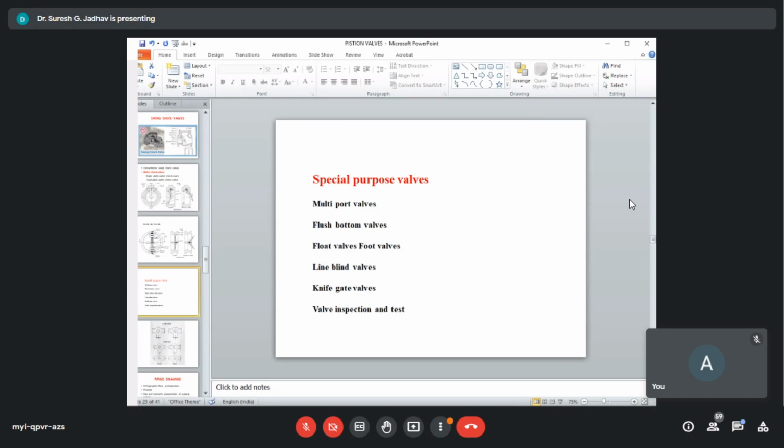There are 2 types of flush bottom valves. The first one is a valve with the disc opening into the tank, and the second one is a valve with the disc opening into the valve. In the first case, the stem pushes the disc into the tank to drain the liquid, and this type cannot be used when there are any internals which restrict the movement of the disc.